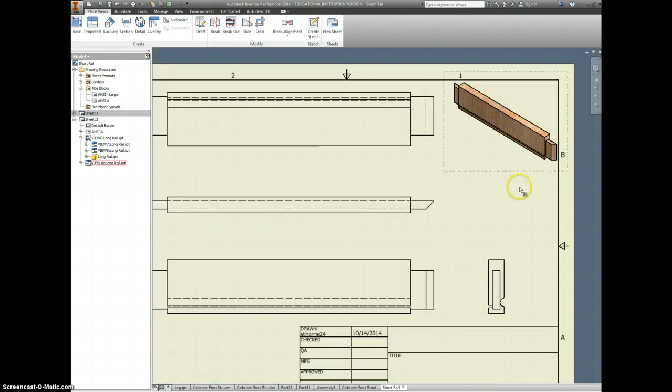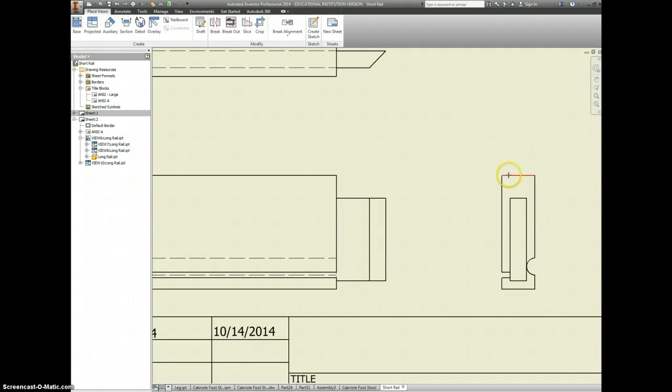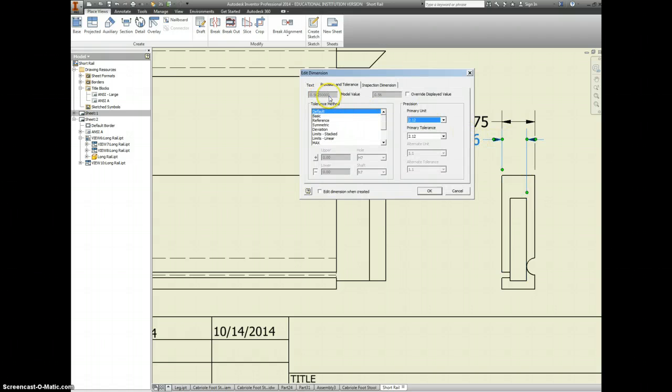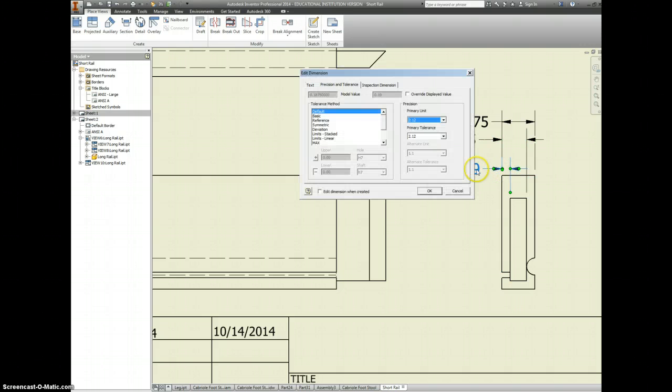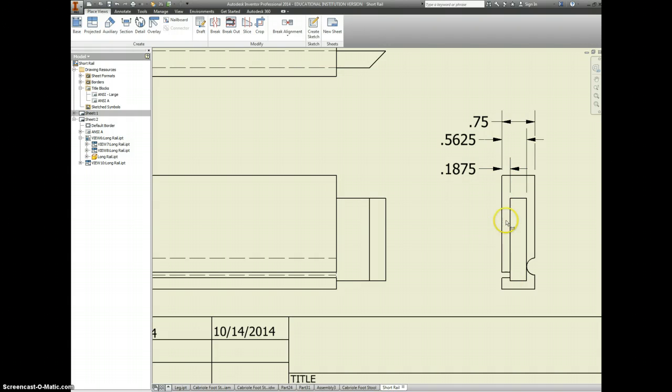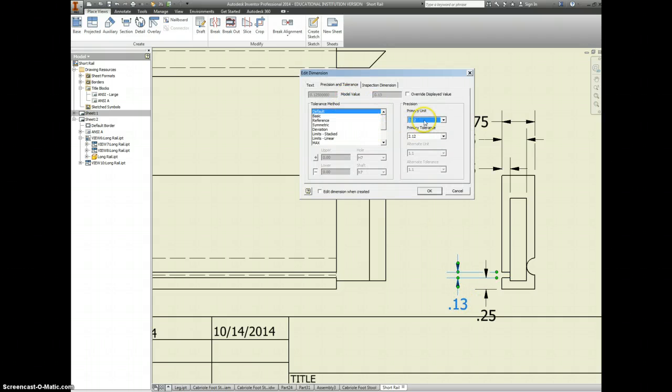You can see the dado there. That looks good. We'll put in the same dimensions we had last time. There's the overall width. We're picking the same datum we had from before. And 6 doesn't look right, so we have to include 4 after the decimal. .19 is supposed to be 0.1875, so put in 4 after the decimal. Okay, then we have height of this is still 1/4 of an inch. Table saw blade is still 0.125, 1/8 of an inch.